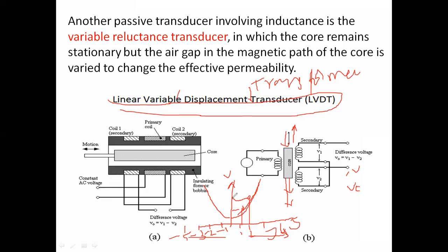Like this, we can get the LVDT characteristics. Up to a certain amount of displacement, it offers linearity. After that, it provides non-linear characteristics.